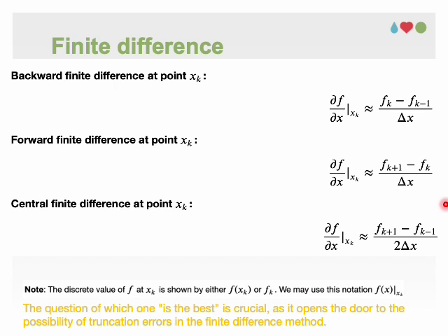Okay, we have seen there might be different variations of FDM depending on the type of differential equation being solved and the specific discretization scheme used. For example, for a one-dimensional problem, at a given point along with its two neighboring points, the central, forward and backward difference schemes can be used to approximate the first-order derivative of a function.